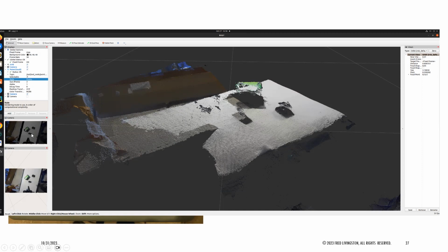And I'm trying to determine the location in 3D of these things here, so I can actually maybe grab that here. But you can see here, there is a point here. I can physically measure that point and get this XYZ coordinate here. So I know my XYZ of this here, and I can pick it up. If I want to pick it up from the top, then I know my rotation is, I want to have my A matrix this way.